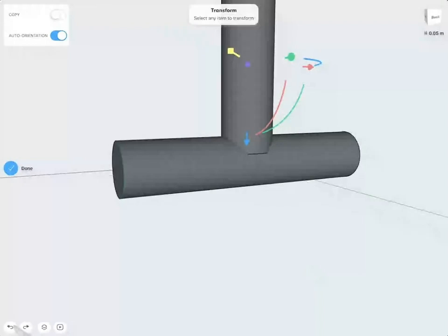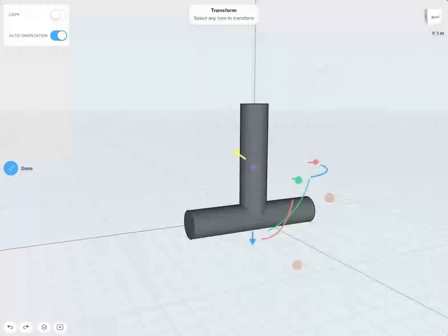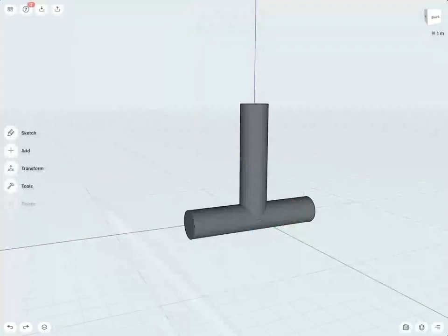So a very good practice in this case is connecting two pipes via a T-section with the same thickness requires that this pipe only intersect this pipe by 50%. Otherwise, as you see, if it's not enough or too much, it doesn't work good.